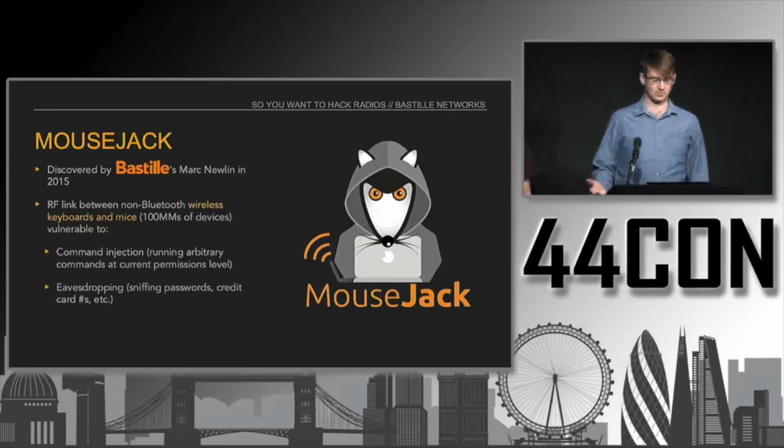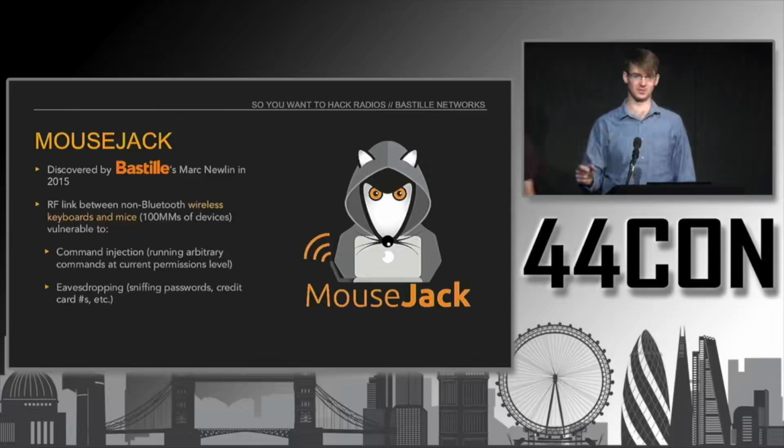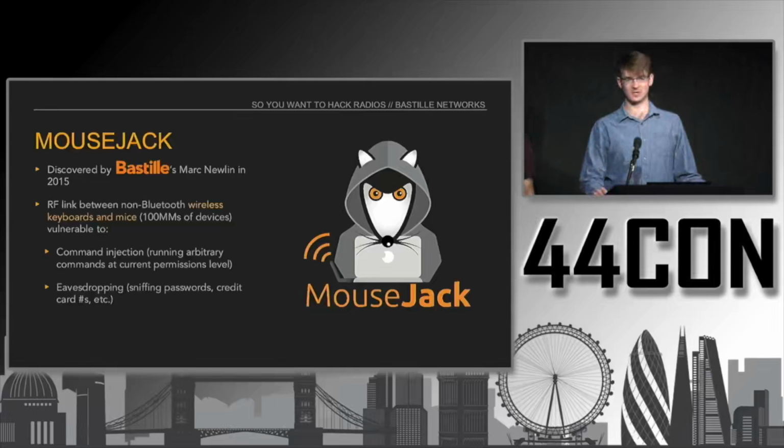The second vulnerability I'll mention is a series of attacks that Marc here discovered in 2015. Marc spent a lot of time looking at the wireless link that connects non-Bluetooth wireless mice and keyboards to the dongle that gets plugged into the computer to connect them. Vendors often use this non-Bluetooth protocol called NRF24 because it's less expensive than Bluetooth. There's no licensing associated with it. However, it really implements just a physical layer. There's no layer 2 and therefore no security built into it, and that's left up to the vendor.